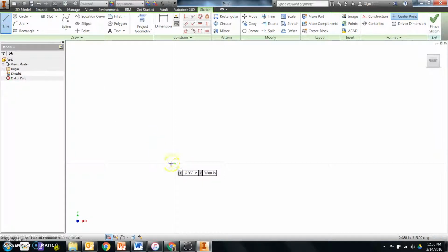line. Now, there are easy ways and simple ways to use Inventor. In this particular case, I think this is just as effective as the other ways, but less efficient. So I've entered for a line to be 0.75 inches in height, and then I'm going to click and move this over to the right by 0.75 inches, and I'll hit enter, move it up another 0.75.